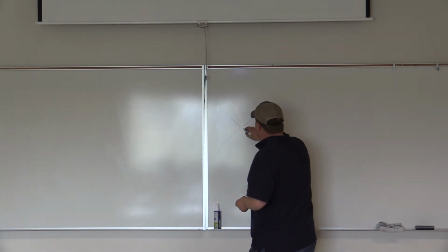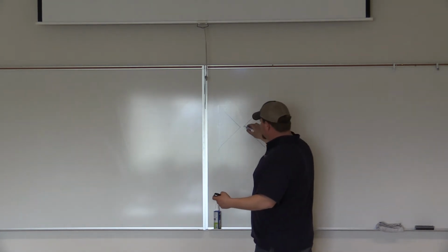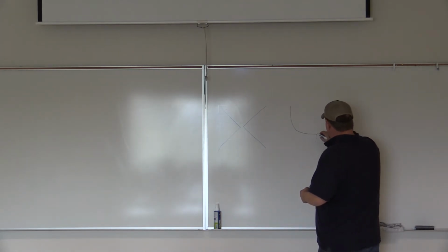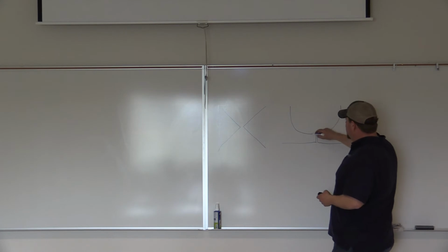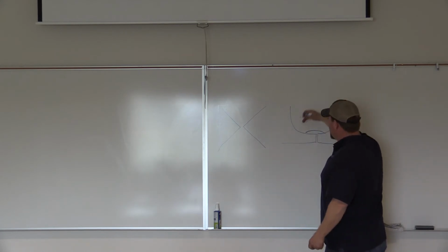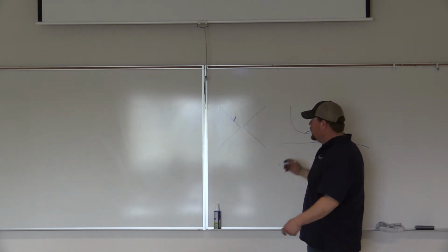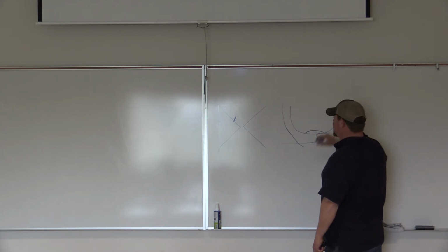Also, if you come as a double bevel, you have a fine point here, right? So something that burns really hot, spray transfer or flux core, this could be a little bit of an issue, versus this one was commonly used for heavier iron, 7024, most shipbuilding, and the weld would come in and you could put a lot of iron in there and it would fill up in a gradual progression instead of taking a chance of not breaking down this edge. However, as you can tell, the heat affected zone becomes tremendous as well.